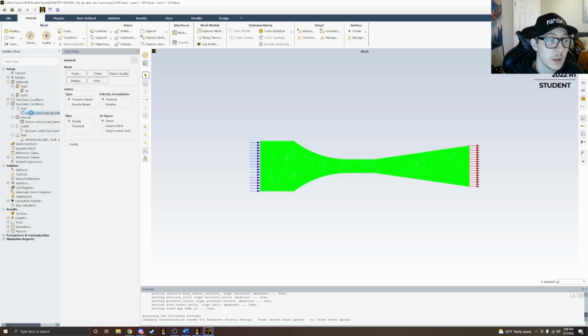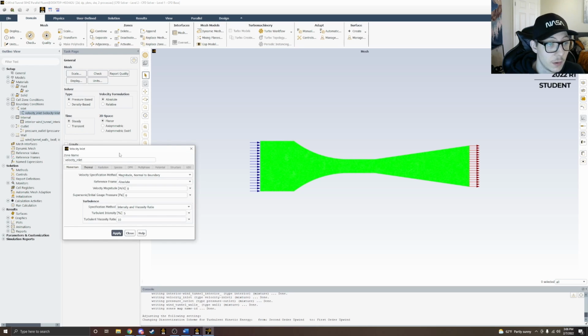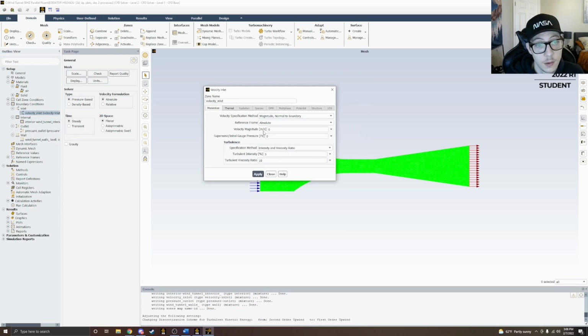We do want to make sure that our velocity inlet, though, yeah. So our magnitude, this is how we're going to actually set up our wind tunnel. So for 50 hertz, I already solved it, 1.34. Again, this is really low speed, 1.34 meters per second. I got more digits. I'll put it in. Why not?